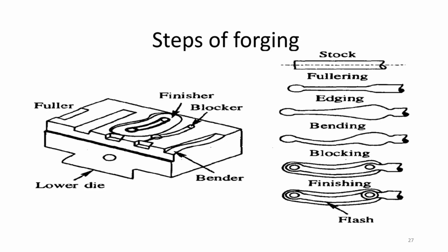Okay, aluminum has more compared to brass, so it has 25 and brass at 19. So in case of aluminum you need to provide an even bigger pattern allowance. But how are you asking for comparing it with the liquid and that order, can you repeat? I mean, when we are considering the solid plus liquid shrinkage, that's actually the total shrinkage, isn't it?